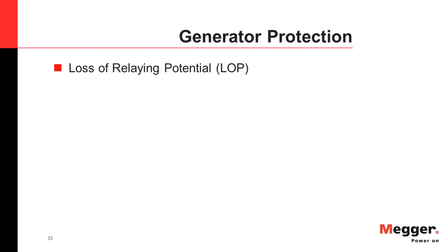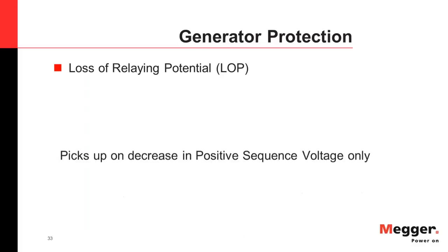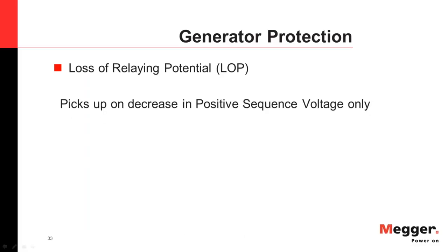The idea behind it is that it detects the blowing of fuses connected in the PT secondary, and that PT is measuring your terminal voltage.